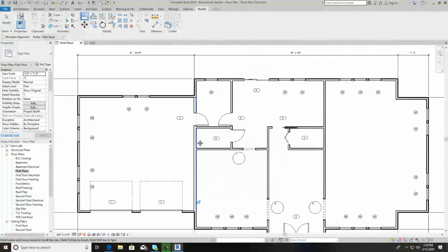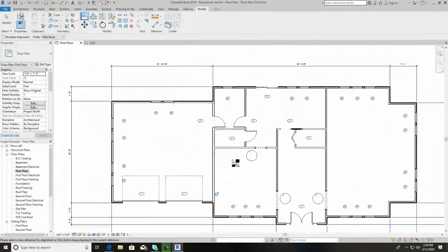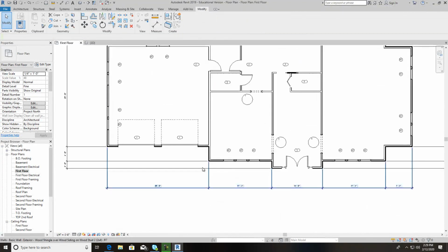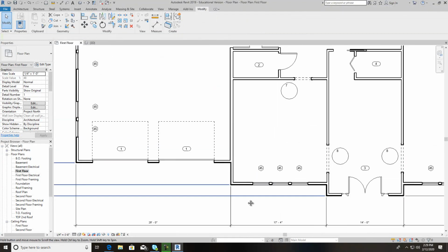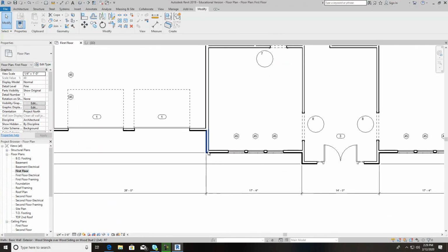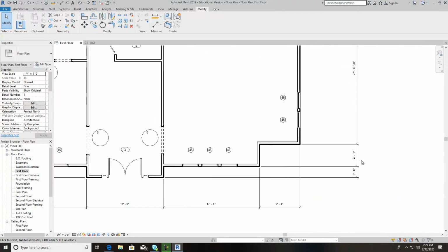And it moved. Yeah, we got all of them lined up now. Now we can make one move. We can even come up here and click on this one and make it 28. And everything's right. And down here, everything should be right because they were 3 separate walls, and we just linked them together with that modify alignment tool. 17.4. All that looks good down here.